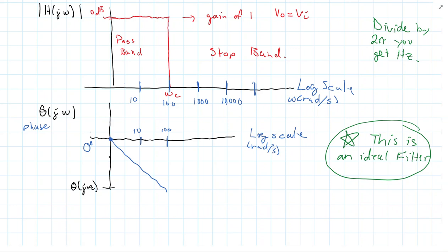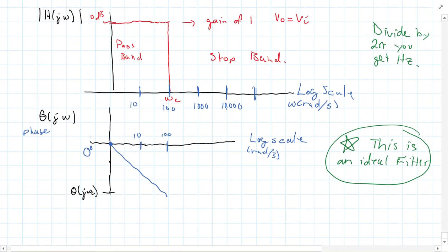And now, with this diagram, we're going to go ahead and start naming these types of filters, and the names go along with what signal is being passed. So the name here would be, well, I'm passing low frequencies through and I'm stopping high frequencies. So this would be considered a low pass filter.